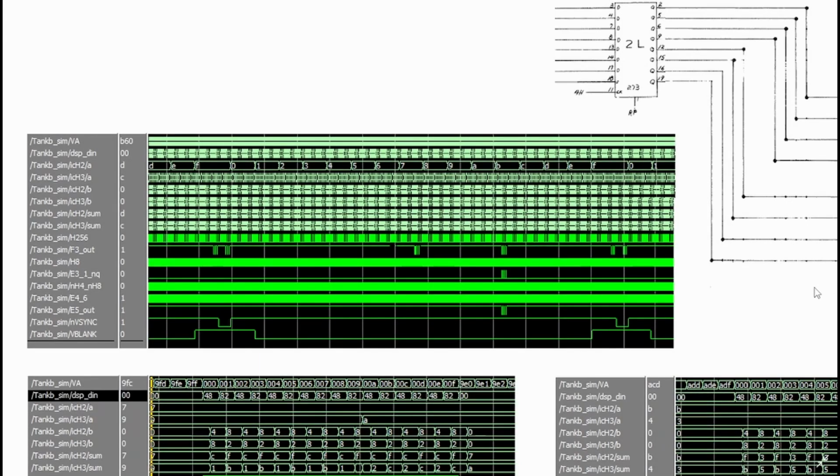Looking at the traces, this first one shows all of the elements of the vertical delay circuit we've just gone through. We can see that this F3 out from the NAND gate goes low 4 times. 1, 2, 3, 4. These two are during the VSync, and they're just actually when the counter equals FC to FE, and they're not looking at bullet data. So this is always going to happen, but it's not relevant because it's during this VSync period, so is just excluded. The other two times we have F3 out as low are the two times when the sum of each vertical and horizontal coordinate is equal to FC to FE.